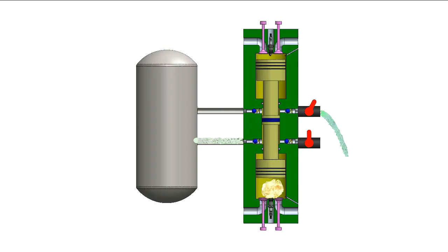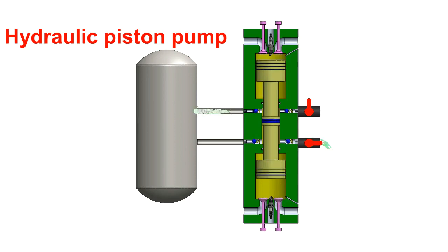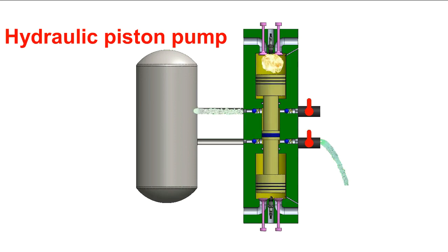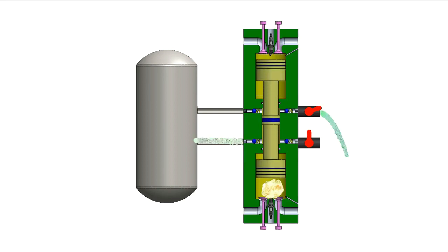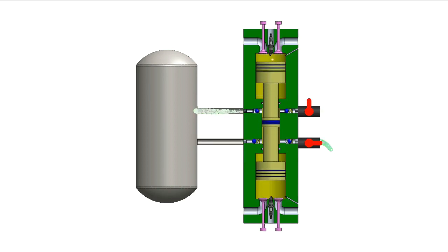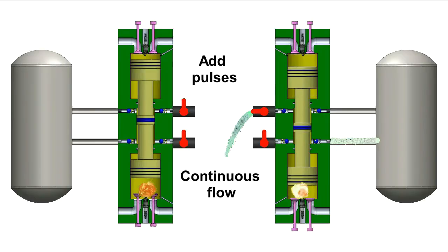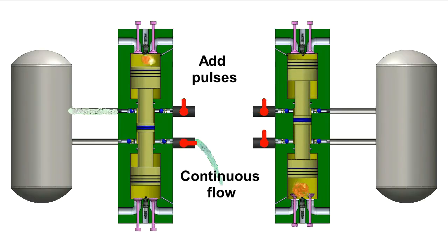What we have so far is a 3-stroke engine that shoots jets of hydraulic oil, so if used to move a hydraulic motor, this motor would turn intermittently. The practical and commercial solution is to use at least 2 3-stroke engines, and add the flows in a way that it is continuous.